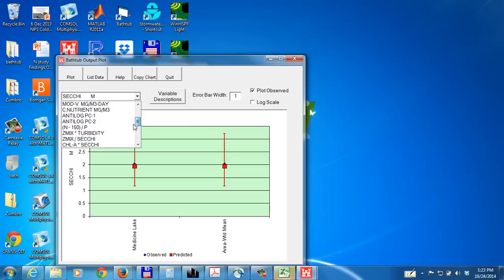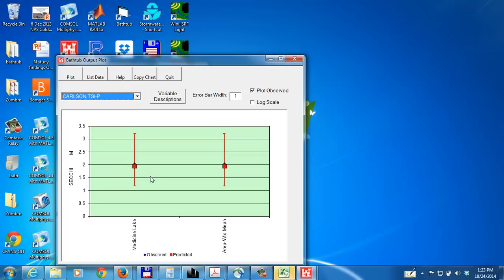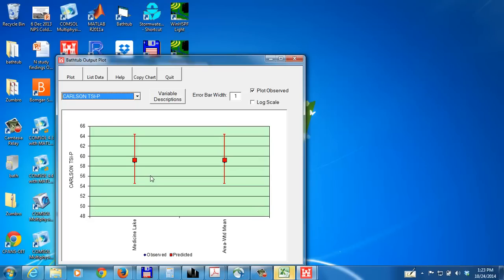And in the assignment, I've asked you to also calculate the Carlson TSI. And there are 3 TSI values. There's one based on phosphorus, one based on chlorophyll, and one based on Secchi depth. And from this, you're able to determine the trophic status of the lake. And I've provided a document from Wikipedia that explains how to interpret the TSI value in terms of the eutrophic status of a lake. I've asked you to interpret that for these 3 segments.